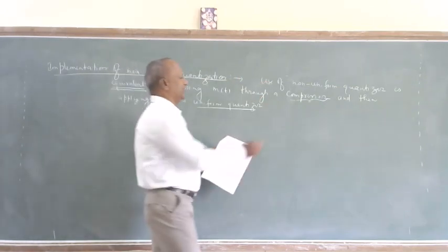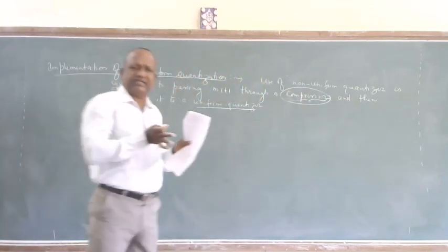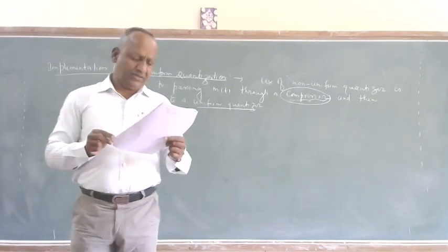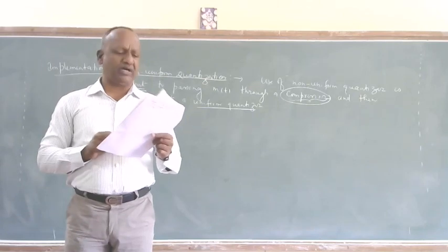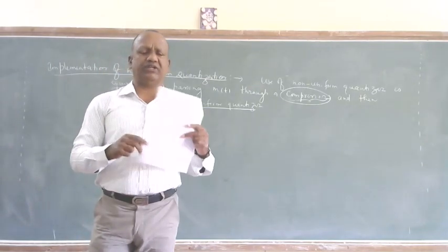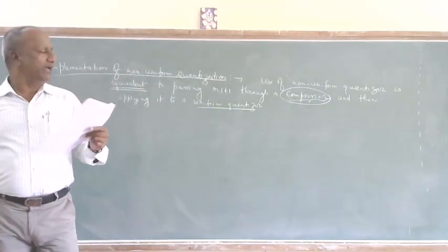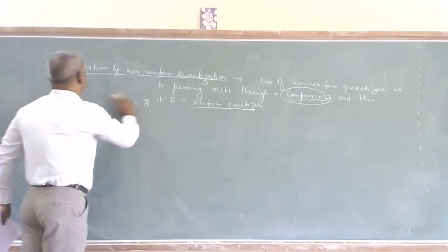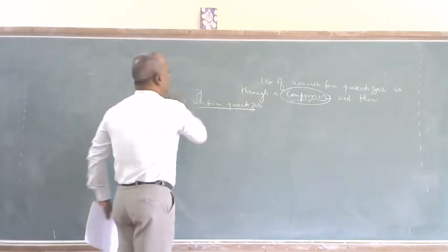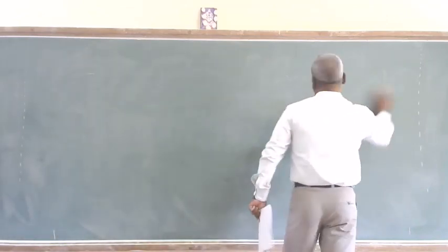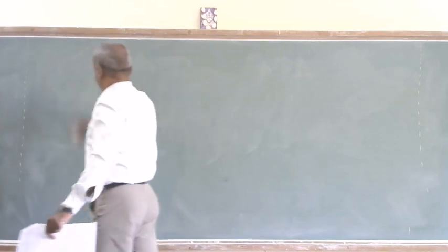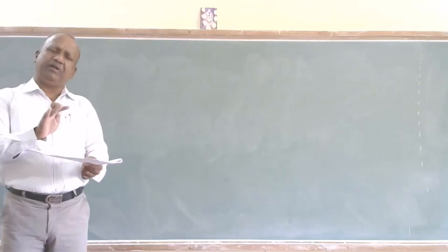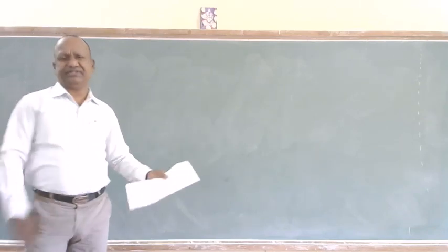Okay, how do we compress the signal? Basically there are two laws to do the compression of m of t. One is called the mu law, another is called the A law. We will discuss those two laws, particularly the mechanism of compression, because it is not a blind compression. We are not compressing the signals blindly. There is some definition or mathematical model, and based on that we implement the compression technique. Similarly, the expander at the receiver side is exactly complementary to the transfer function of this compressor. Opposite process.